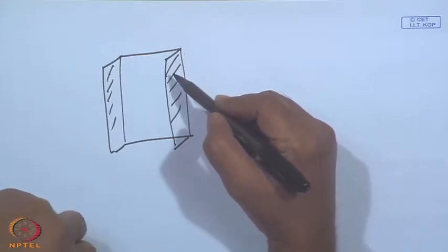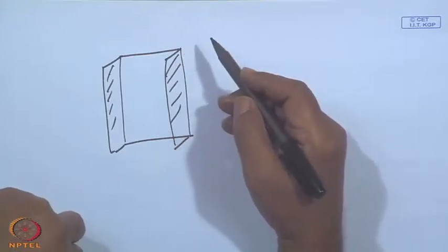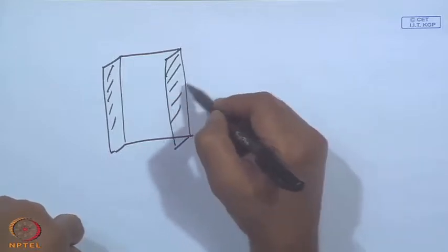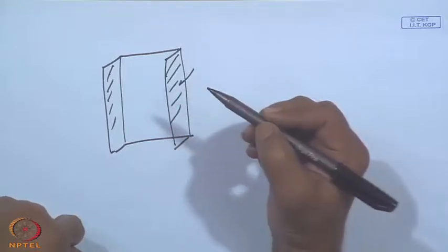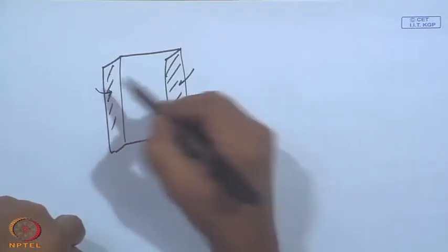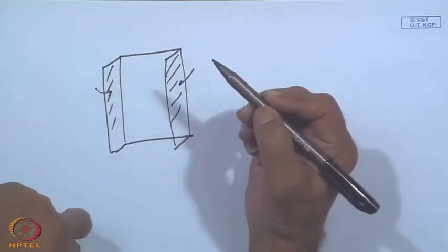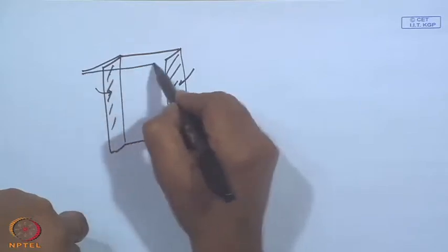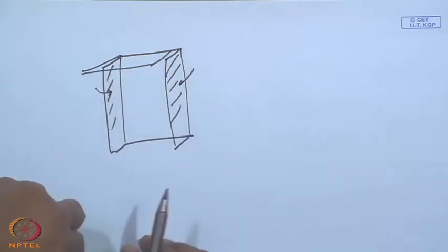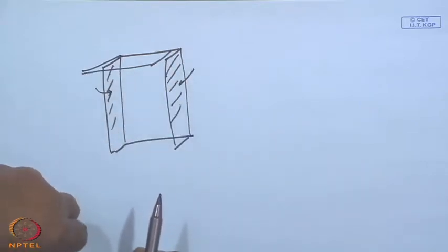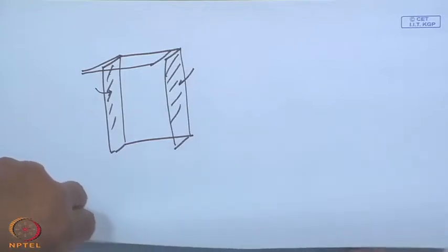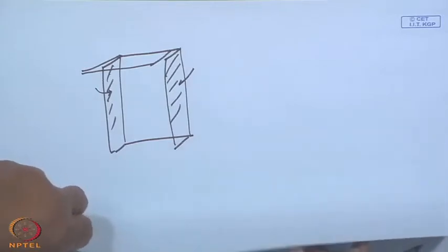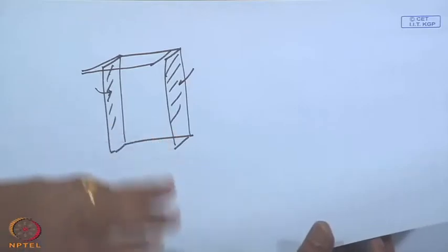But these wing walls prevent a lot of radiation entering in the morning if it is in the east and in the afternoon if it is in the west. So, in conjunction with an overhang, effectively it looks like a box type of window which will be completely shaded. Whether you desire that or not depends upon the season, climate and your objective.